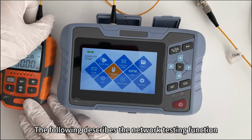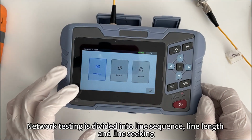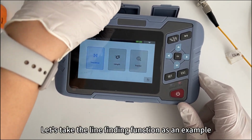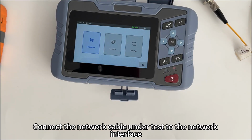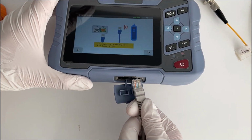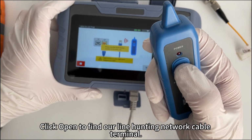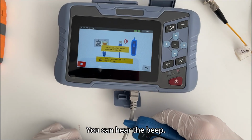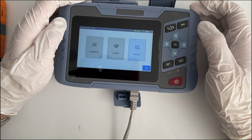The following describes the network testing function. Network testing is divided into line sequence, line length, and line seeking. Let's take the line finding function as an example. Connect the network cable under test to the network interface. Click Open to find our line hunting network cable terminal. You can hear the beep. It can be judged as the target network cable.